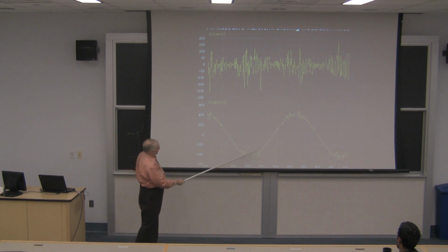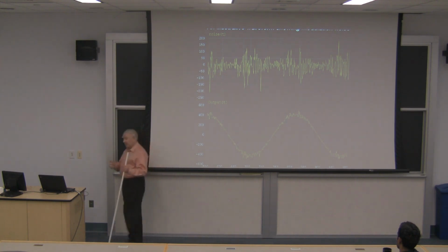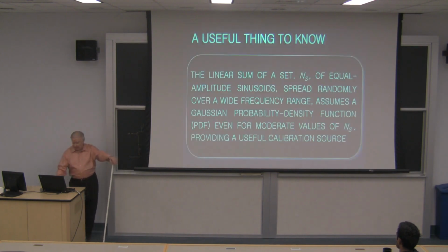And we can see that, as the sinusoid pushes towards some input limit, 400 millivolts, I think it is here, so the modulation noise increases. And again, this is a very deterministic thing. It's very easy to document and calculate and so on, but we're not going to do that today. If you want to talk about it.